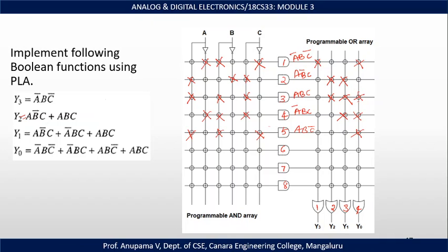Now see here, none of the gates are unused, unlike PAL, and also I can reuse the AND gate output for the OR gates. So these are the advantages of PLA over PAL.